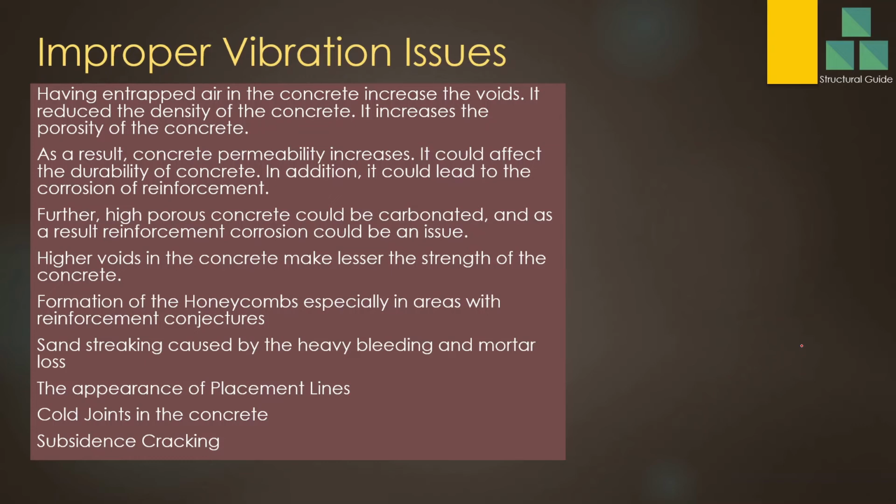Honeycomb formation, especially in areas with reinforcement congestion, could occur. If you have a highly congested reinforcement area, you have to be careful and do adequate vibration with close inspection and close supervision. Otherwise, internal cavities may form, or honeycomb that appears on the outside will be there. Sand streaking caused by heavy bleeding or mortar losses could also occur.